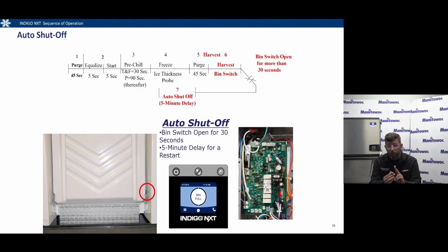Verify the install, so things like being level, the adjustment of the ice probe, make sure you're making a good sheet of ice, and the third one is, is that ice machine clean? If it's not clean, scale will slow us down while we're sending heat to the plate. If we slow down, we continue melting. If we melt enough, we lose our weight. Once that starts sliding forward, you don't need refrigeration anymore. You need 2 things: a smooth, undamaged, level path, that's 1, and weight, that's the second.